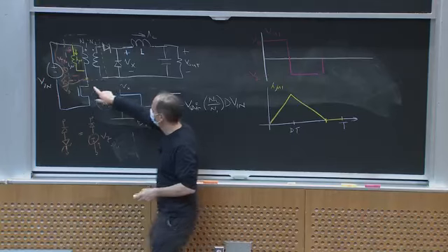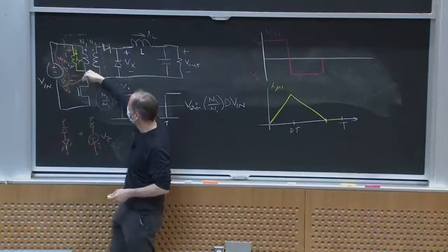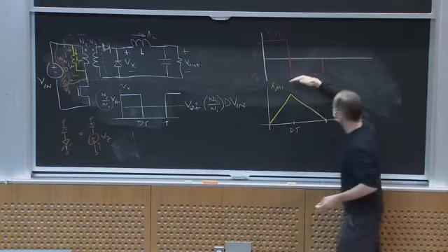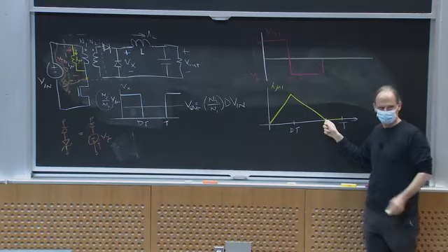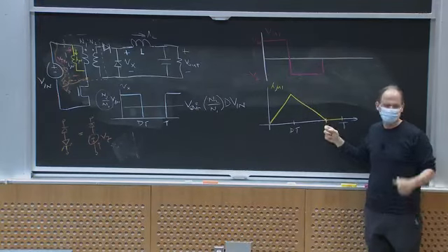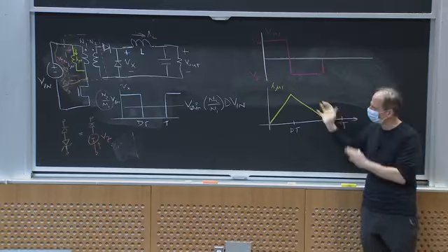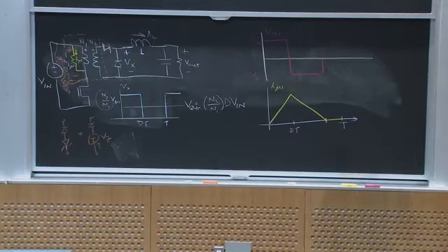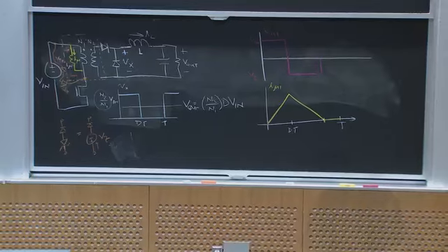But essentially, I just got to give this current a path to flow into a voltage source that's going to apply enough negative voltage to drive the magnetizing current to 0. A lot of ways I can do that. The Zener was just sort of my model for the easiest one to show you. Does that explain things? Other questions?